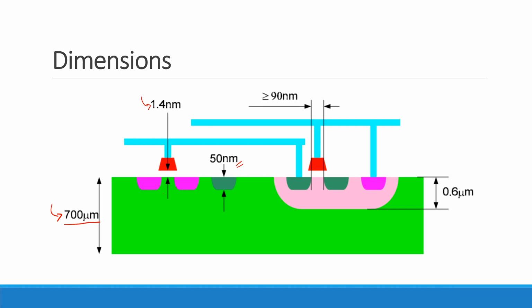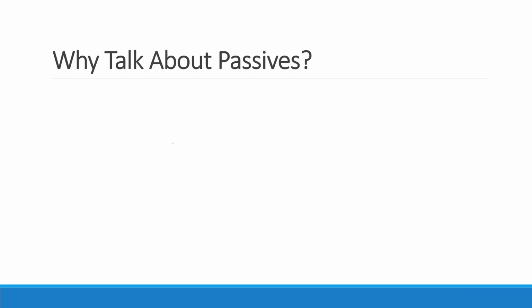So these days, it's actually quite common to take the silicon wafer, once it's been processed already, and literally shave off the backside of it to knock this down to something smaller, let's say 100 microns or so. Again, that's just so that you can make the package thickness of the entire thing at the end of the day thin enough that it's usable in these really form factor constrained applications. Okay? Again, that's just the whirlwind overview of what our technology looks like. Obviously, there were a bunch of layers that I didn't draw there, but that's just to get everybody level set onto the same page.